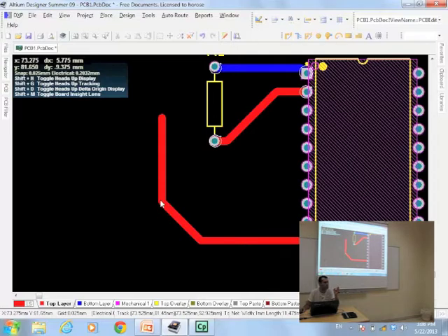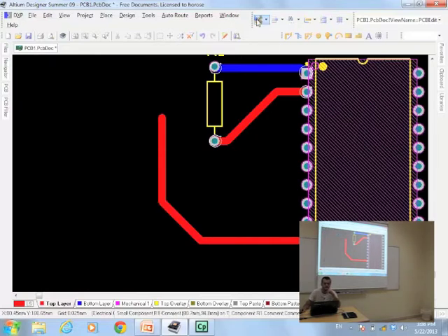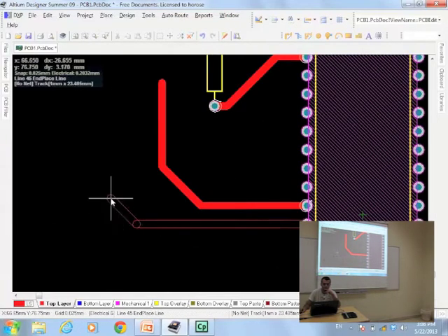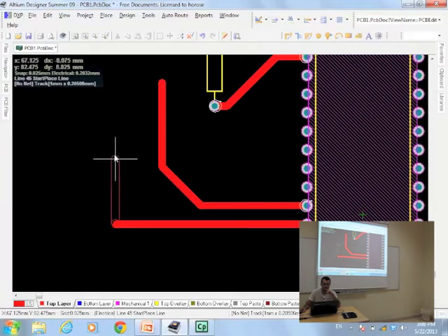Avoid pointy things on your PCB. Try to increase your angle to avoid being pointy. Do not go, for example, 90 degrees or less. These things are not fine. So why do we need to avoid pointing? Why do we need to avoid the pointy thing? One of the things, let me show you something.